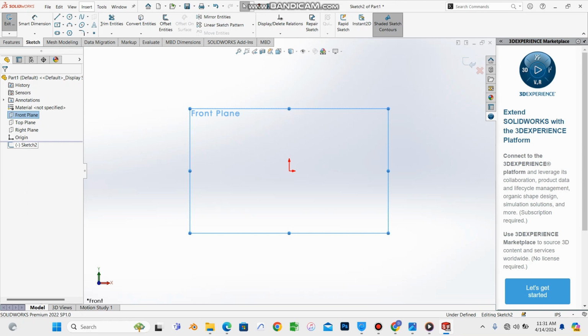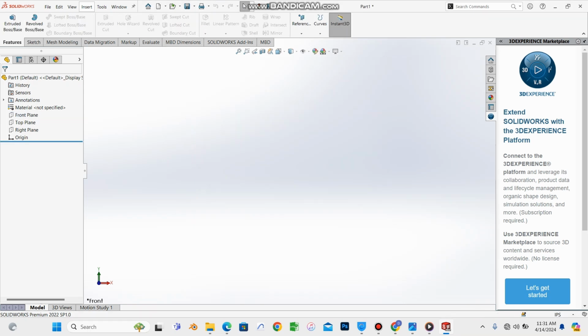This is sketch 2, because we already deleted sketch 1. SolidWorks keeps track of those sketches and parts. So let's cancel this. If you just want the plane to face you, use the normal tool before trying to use a sketch.